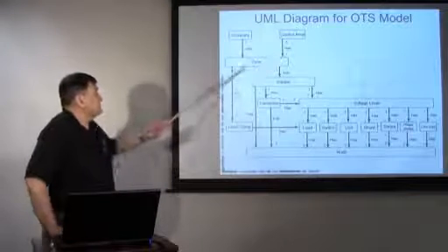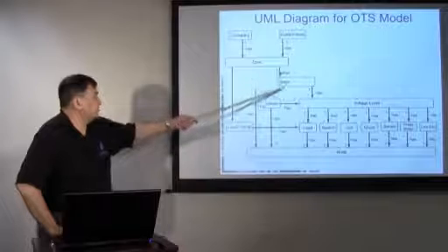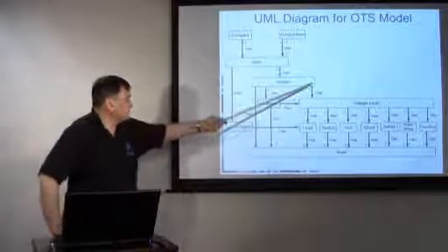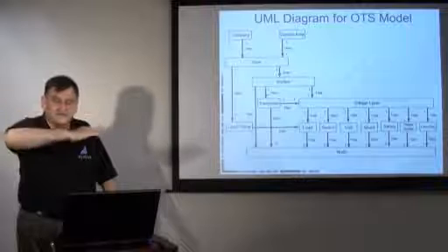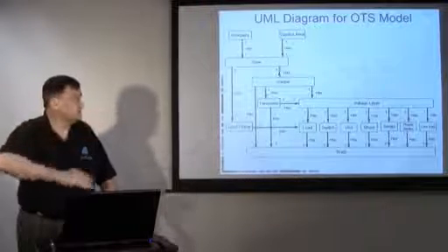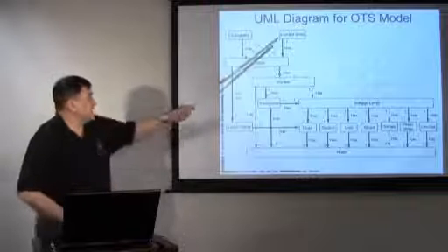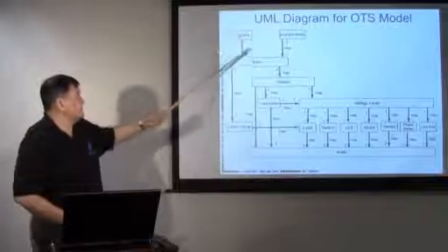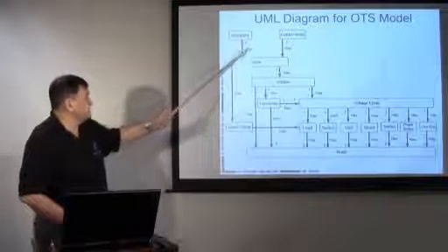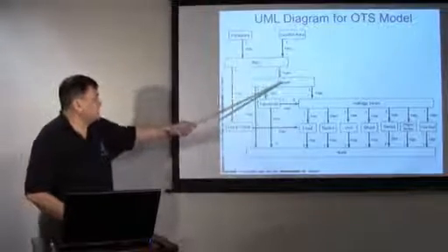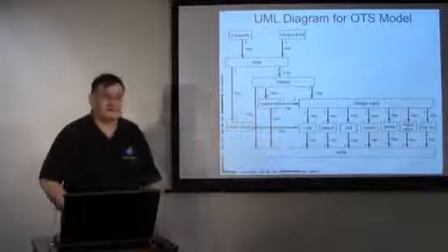So we have zones. Every zone can have a load forecast, and the station is within a zone. And within that station, you can have different voltage levels. Your equipment is definitely at one voltage level or another in terms of the nominal voltage. And so they take advantage of that. So this is like a hierarchy of ownership. Company owns zones, zones own stations, or companies have zones, zones have stations, stations have voltage levels, and voltage levels have various types of equipment.